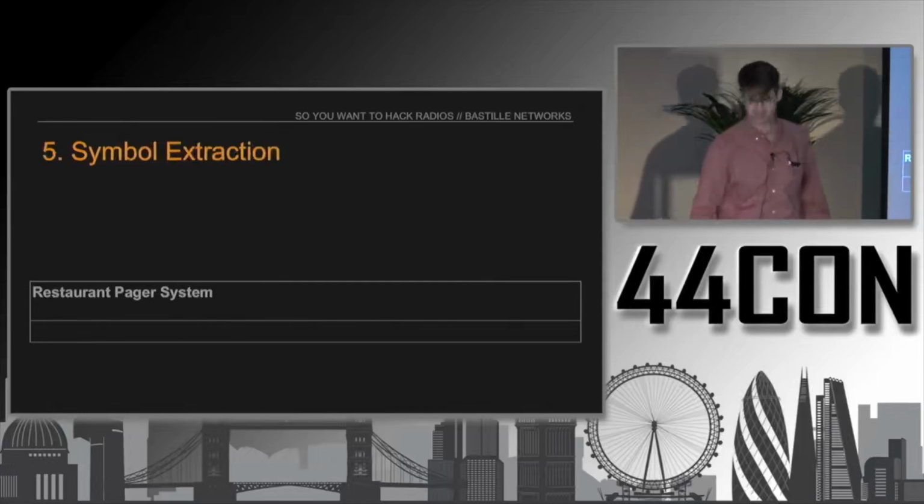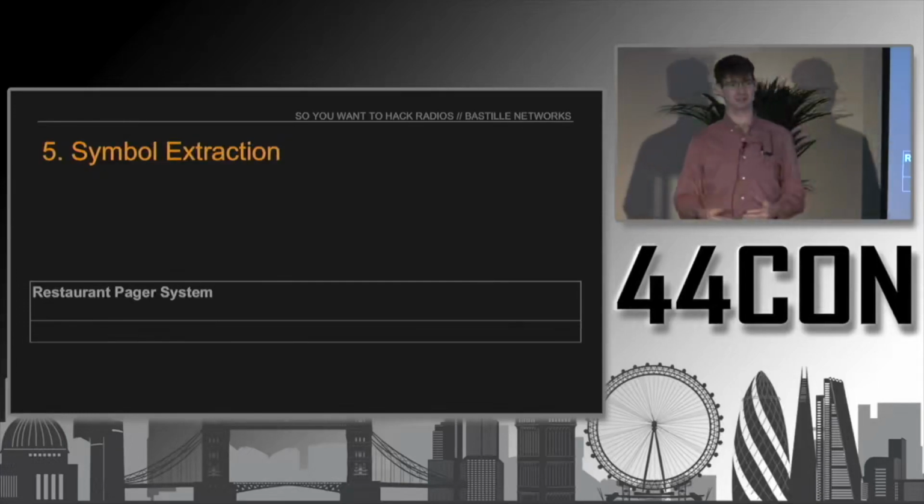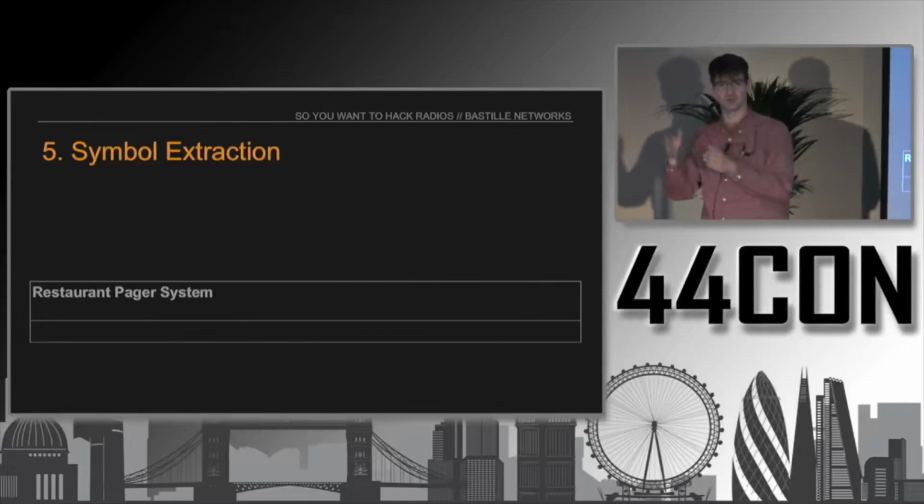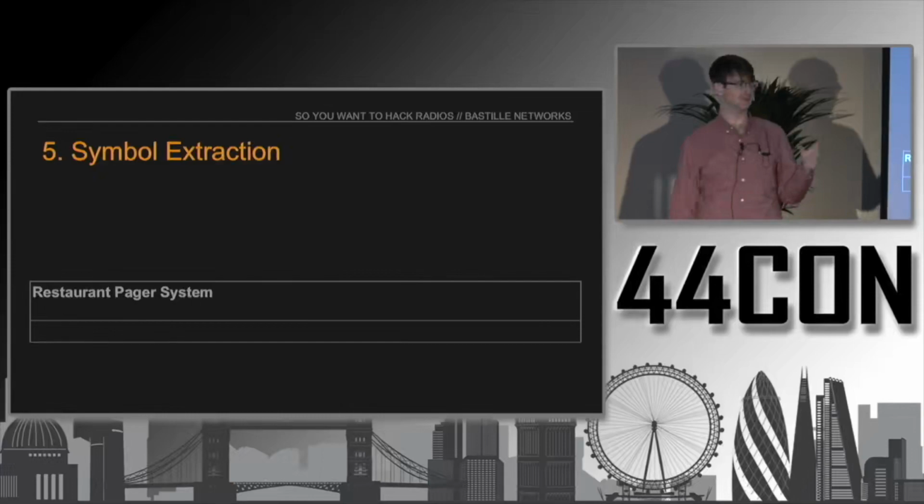Finally, step 5 is to extract the symbols and do the decoding, which we talked through, mapping 8 hex and E hex back to 0 and 1. Then you visually look at the packet while you fiddle with parameters to see which fields control which parameters in the packet, which we saw by the changing addresses within the 3 packets that we pulled out.